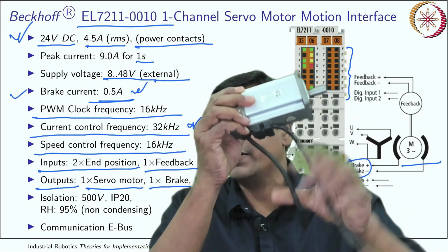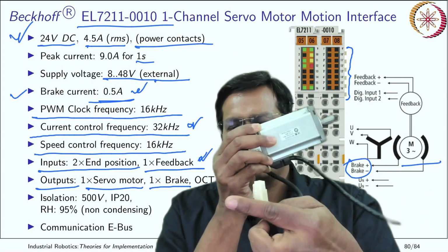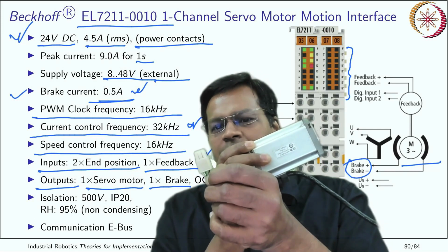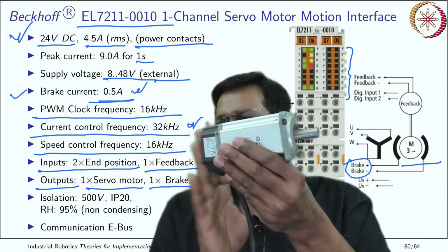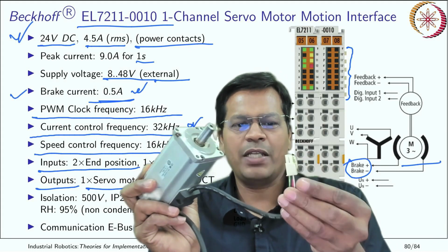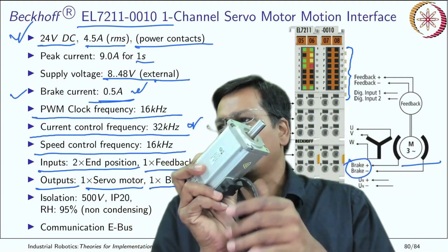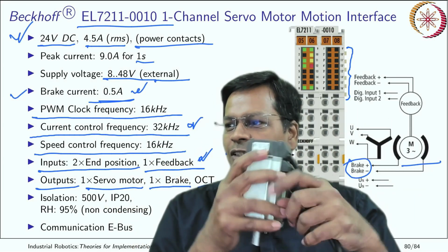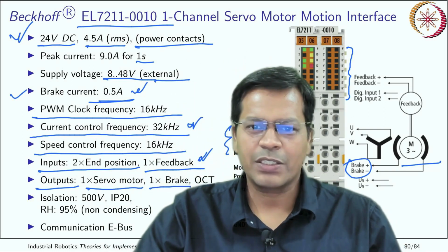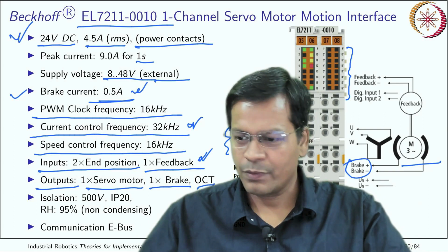So you have 2 separate wires. This one is for the encoder wire. I can see plus VCC, ground, and 3 signals. So it may be a kind of resolver which gives you an output in 3 different wires. And then this is 3-phase and 1 ground, 4 wires. This goes to the motor part of it. So yes, this is how it looks like. This is a Panasonic one. There are many other makes which are making this kind of actuator. So let us go back to my normal form. Okay, I am back.